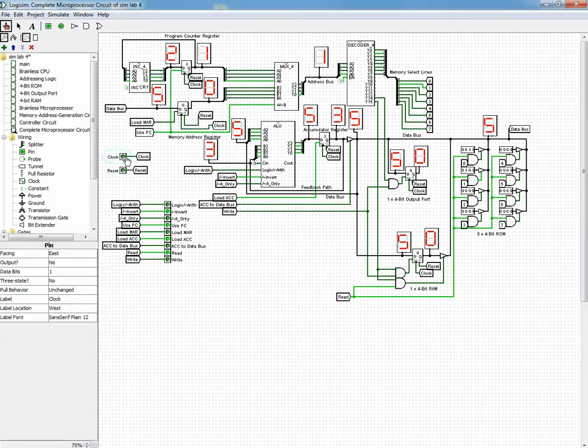So right now we have a 3 over here, which is stored at the accumulator register, and we have 5 coming from this memory unit. So right now we want to put the A only to be 1, so that this arithmetic logic unit becomes an addition. Previously it was a pass-through, right now it's an addition, and we tick the clock again. So right now the 8 has been stored at the accumulator register.